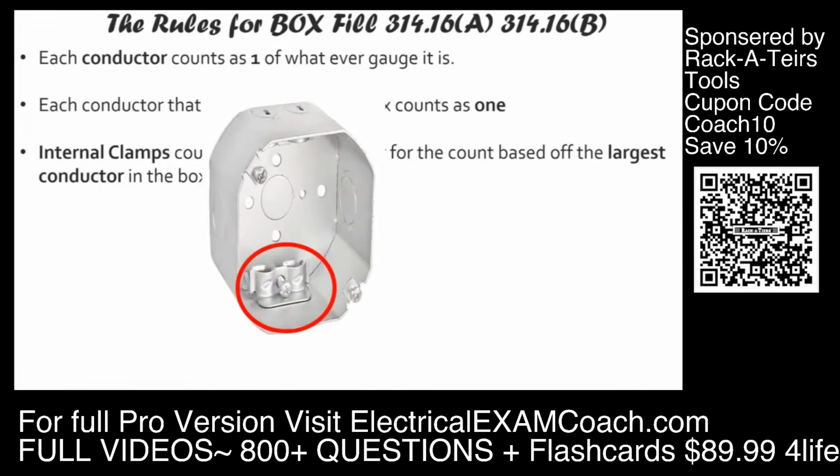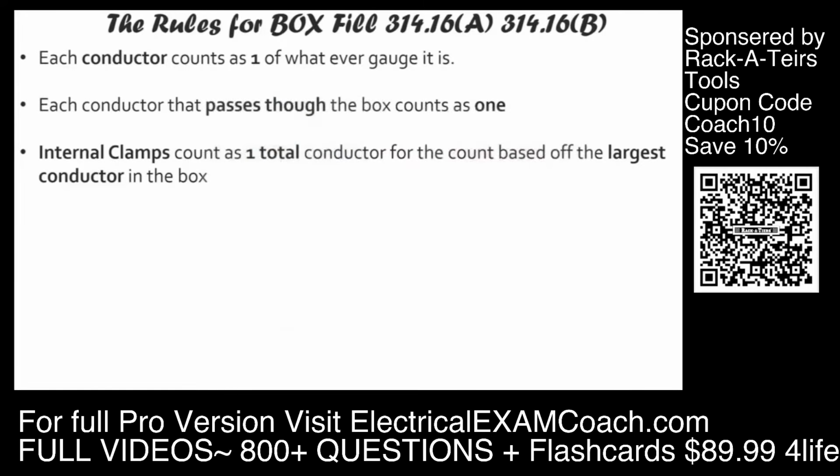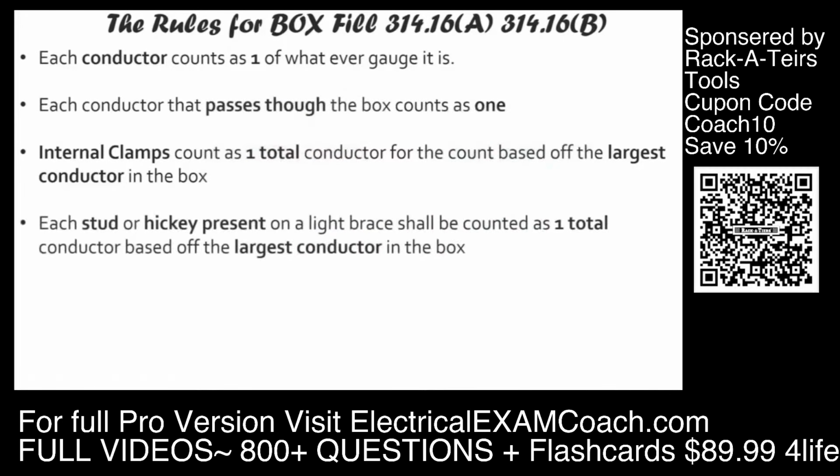All of the fittings we're going to convert over to conductors, then the conductors we're going to convert over to the cubic inches, and you'll know more of what that means as we go through this lesson. This is an external clamp because the clamping mechanism is on the outside of the box, and we don't have to count those at all for box fill purposes. Next, each stud or hickey that is present in the box shall count as 1 total based off the largest conductor that's in the box.